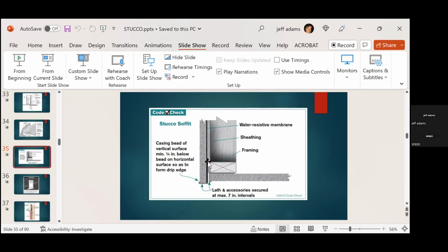But they do make a plaster stop here with a 3.5-inch flashing detail. It's actually made for eaves and stuff, and it works pretty well for this. We just don't want that turn up, and it may have a turn up there of a 1/16 of an inch or something like that. That's fine. And they typically have big 1/2-inch holes in there for the eaves one, so it will work as our drainage plane, and it keeps us as a 2-part system here. Okay.